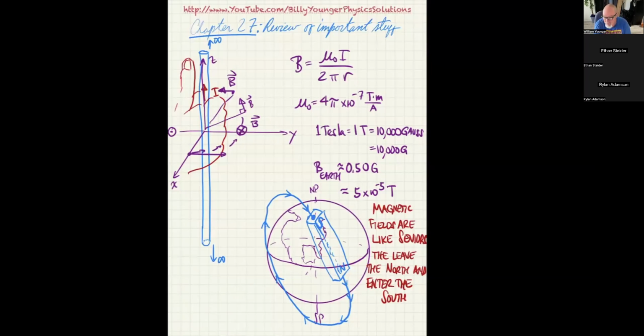So they sell maps that tell you, for the area of the map, exactly which direction points to the magnetic North Pole, and what the real north is, to correct for it. You can find out on your map. It might say like 15 degrees. You'll see a photo of it in this picture.